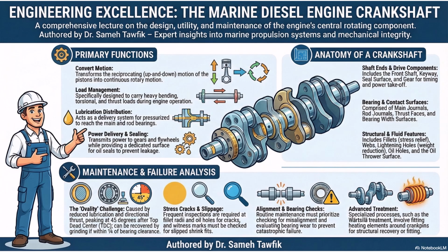This raises an important question, one that goes beyond the specific mechanics of a powertrain. I want to go back to the concepts of witness marks and ovality that we explored in the forensic section of the text. We discussed how immense repetitive directional forces, specifically that localized lateral thrust at exactly 45 degrees after top dead center, gradually reshape even the hardest, most wear-resistant steel. Right. If the lubrication or the environment fails even slightly, the invisible cyclical stress leaves a visible, permanent, and readable history on the metal. I'd like you to ponder how that concept applies to the broader physical world.